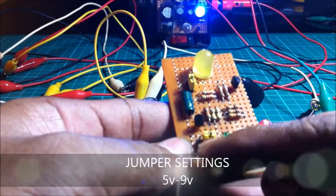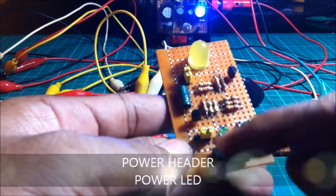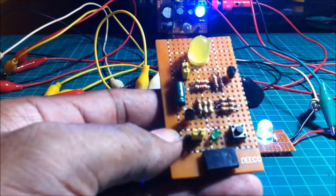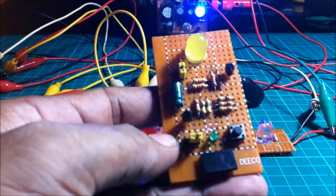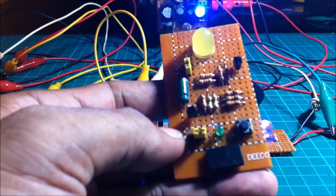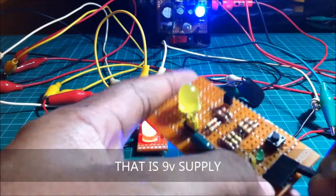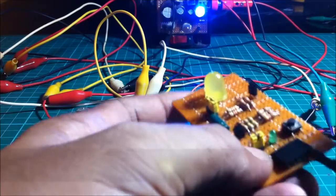We have the jumper settings also for 5 volts and 9 volts. Power supply header, power on LED, and some resistors. So let us see how this circuit works. Let us patch the 5 volt supply, and then the negative one.